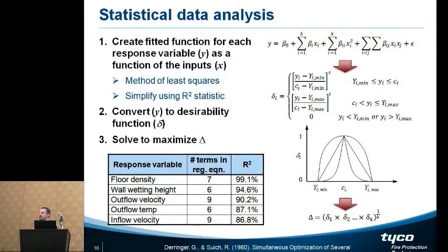We'll say it's okay, say if the target value is 1.8 meters, plus or minus 10 centimeters is probably okay. And that could be based on experimental uncertainty, or on good engineering judgment. We allow it to vary that much so that we can create this composite desirability. You can see this is a piecewise function: at our min value, we're at 0 desirability, we hit our target, we're at 1, and if we go above our target, we get back down to 0.